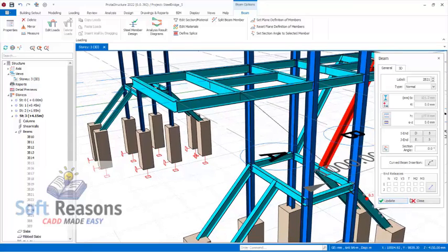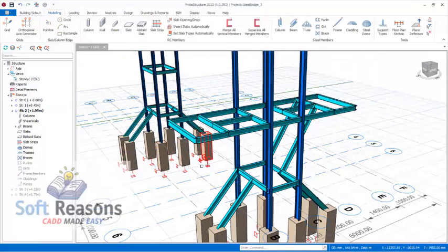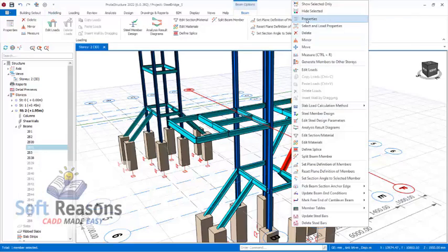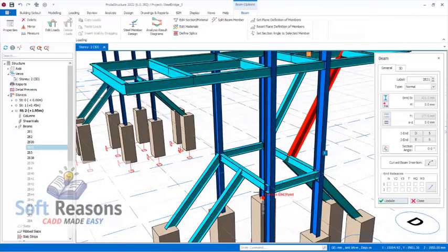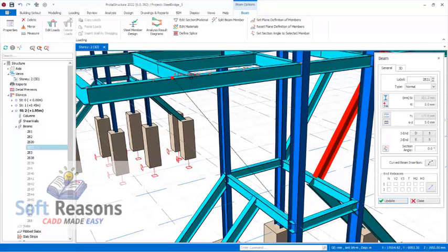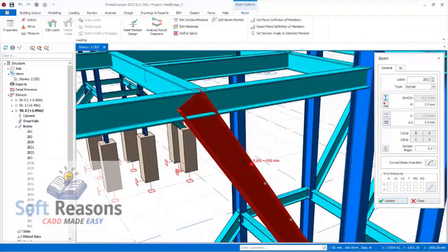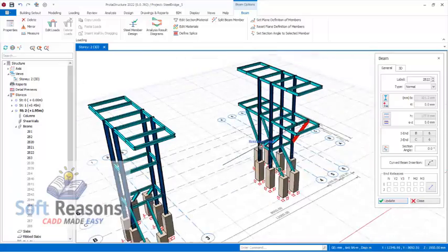We may not be able to get it like this, so close this and move the green lines to the story 2 right there, and then we use the same member property. So now we can select the green line intersection successfully, and then all the way to this point of intersection. Yes option, have that successfully.